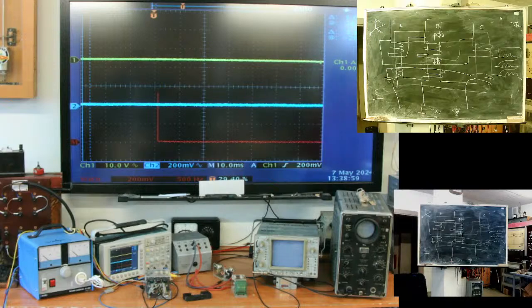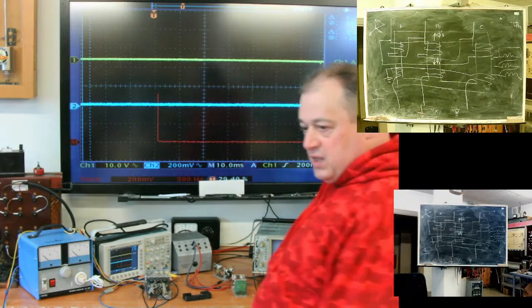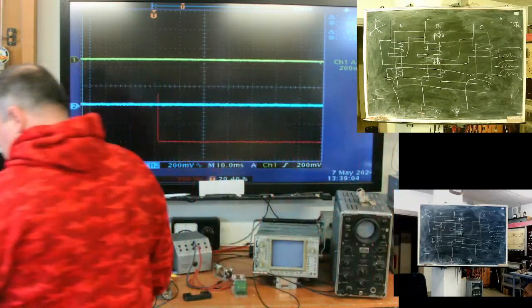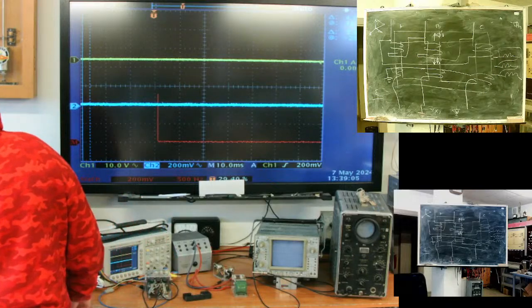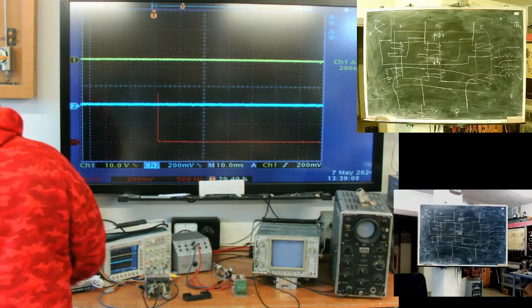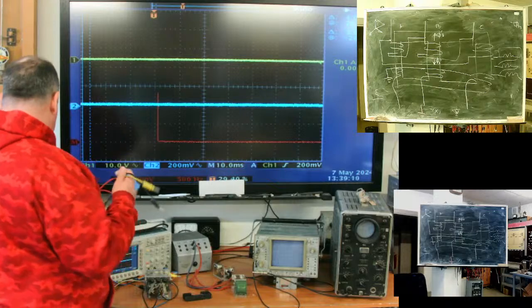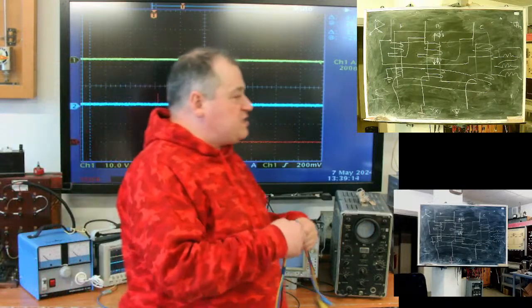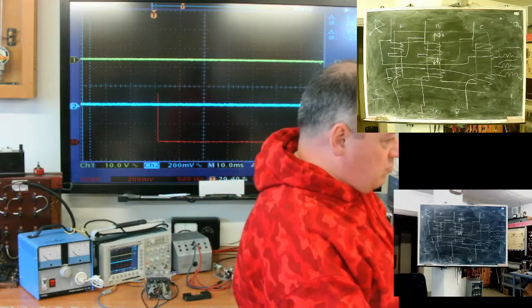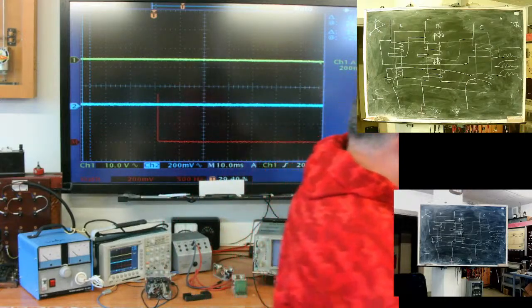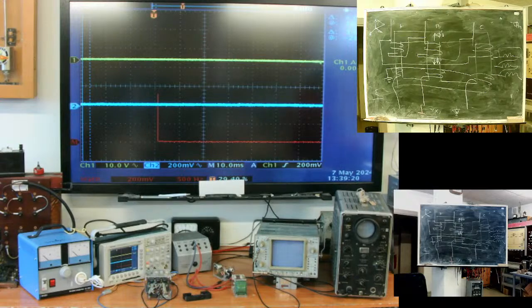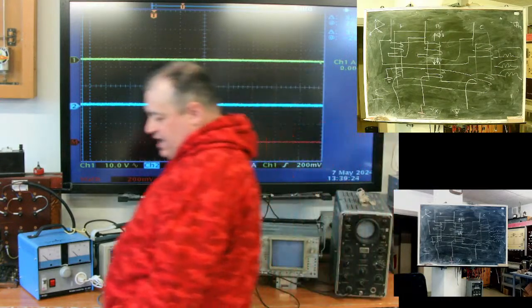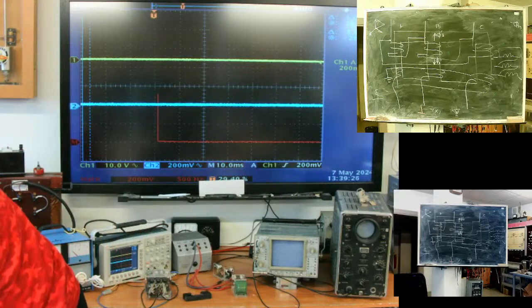At first moment, the 150 Hertz, third harmonic component of the magnetizing current, cannot flow, and it appears that there should be a third harmonic or 150 Hertz component in the flux.